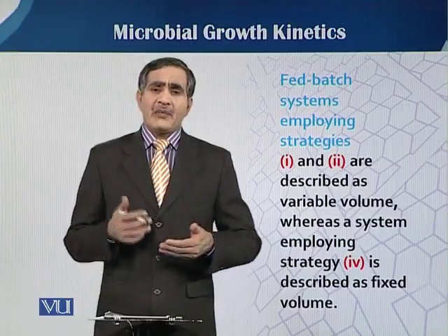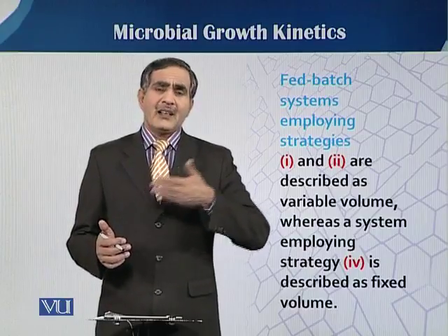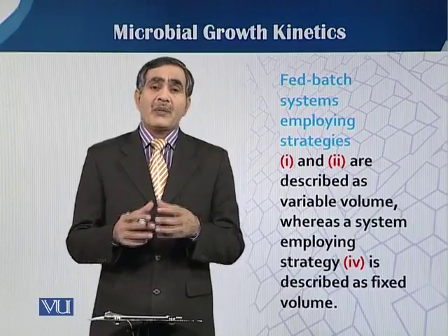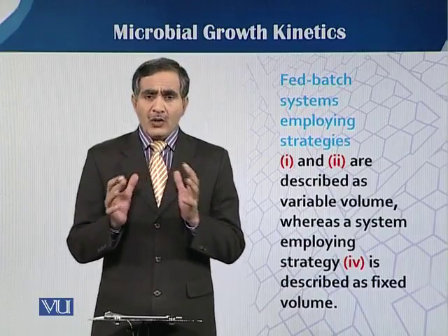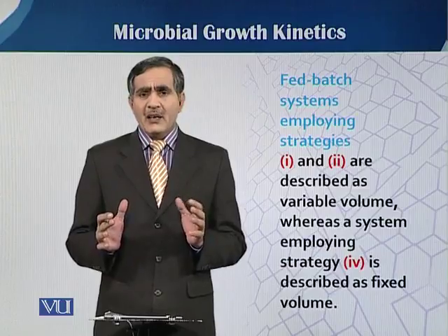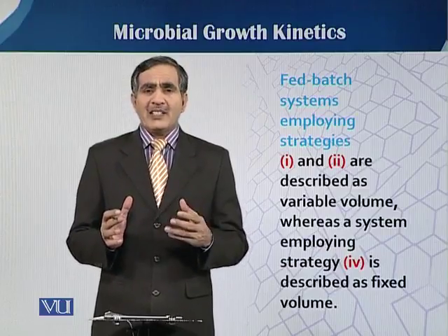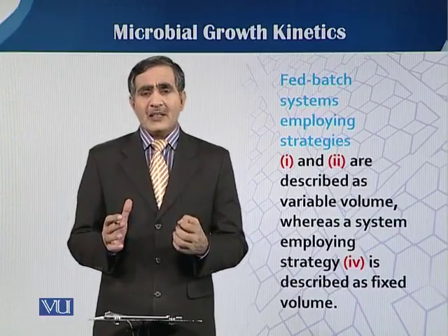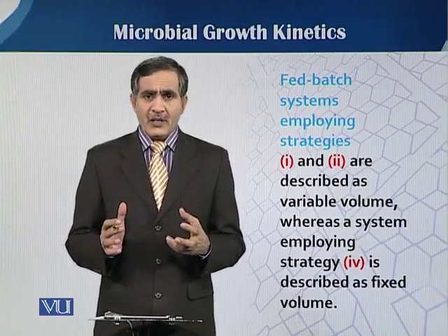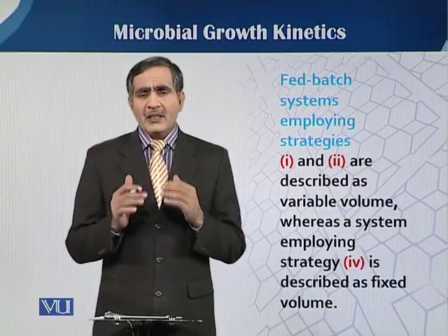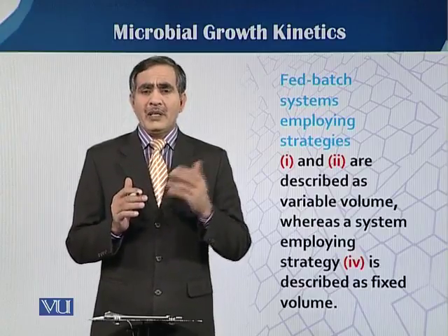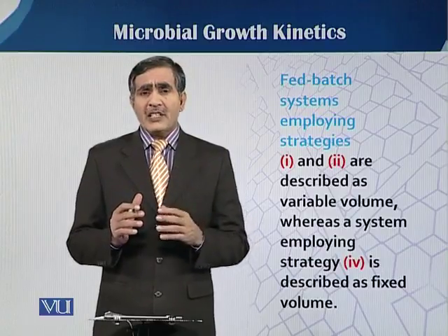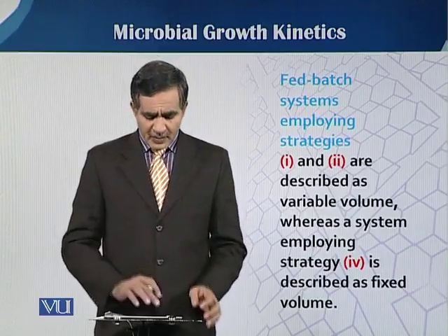Why are we talking about variable volume as well as fixed volume? Because when we talk about fermentation kinetics, volume has a critical effect on the concentration of biomass with respect to time, the concentration of substrate, and the concentration of product. If the volume remains fixed, the kinetic parameters will be different compared to a fermentation in which the volume is variable.